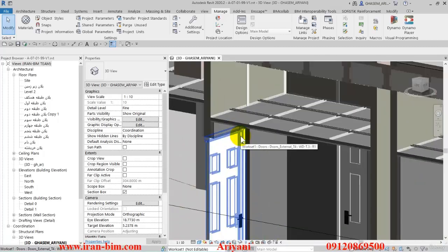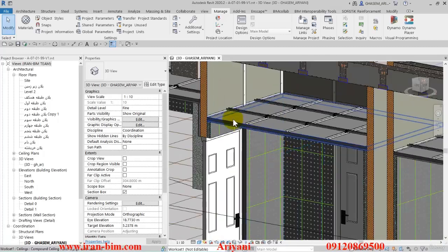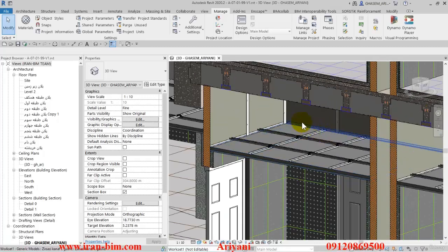So a point that we've already stated in the previous sections is that we never complete the suspended ceiling before completing the mechanical aspect. We may create a flat ceiling based on the height that was set in the architectural plan, but we won't give it any details. We'll leave the details for after the mechanical work has been done.